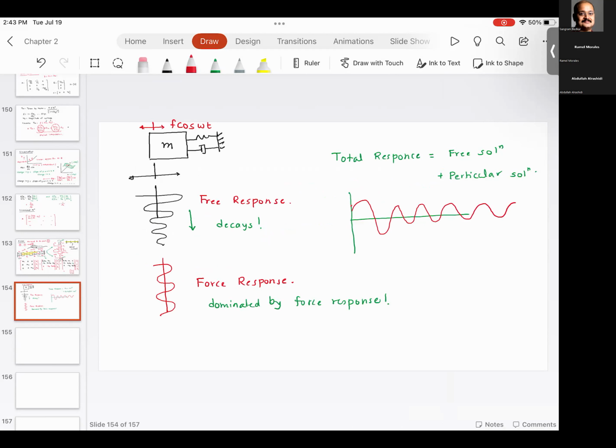And this forced response is actually a function of multiple things. It is a function of the frequency. It is a function of the amplitude of forcing. And it also depends upon whether there is a resonance taking place or not, which means is there any energy interaction where the work done by external forcing is exciting any of the system's modes.